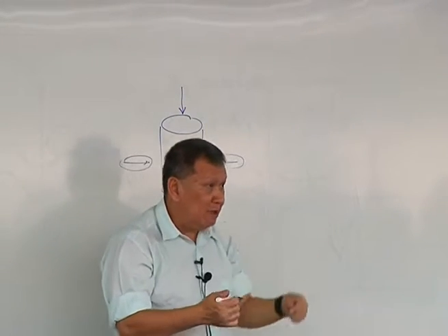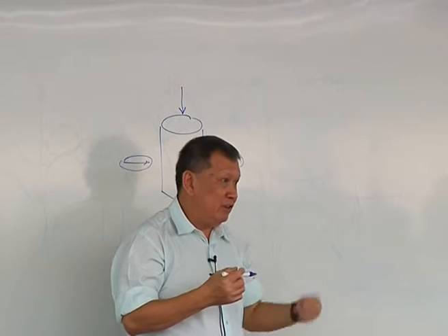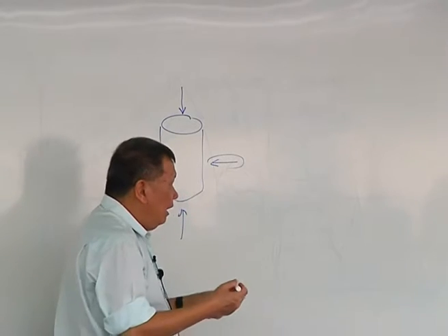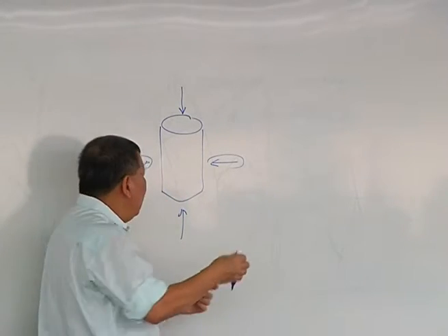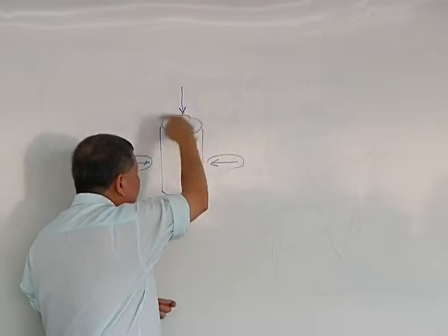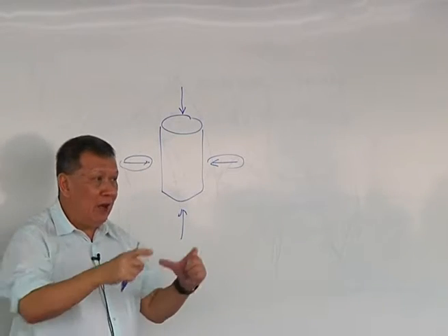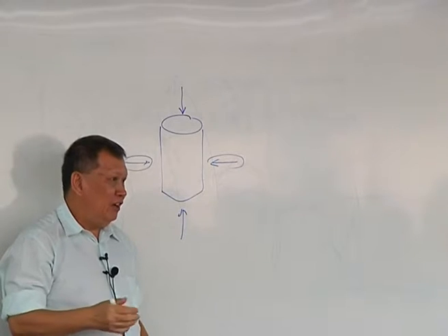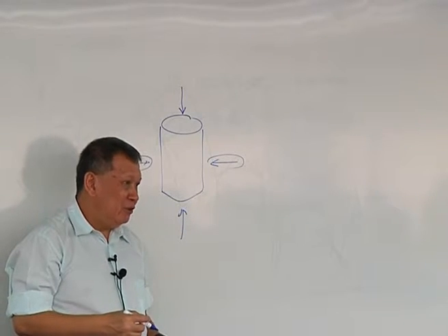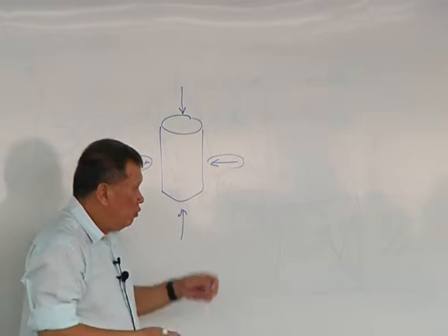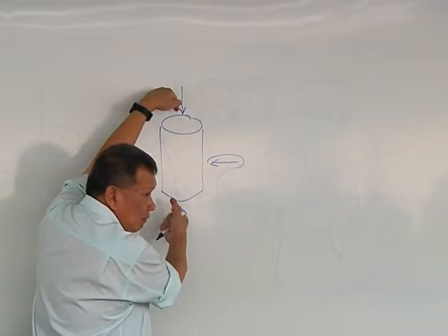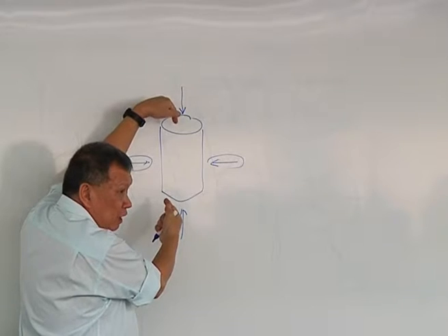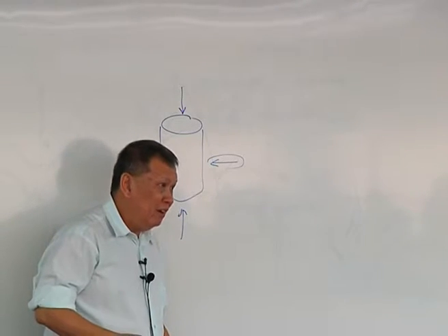Okay, basically you unload, there may be some yielding, and then you reload, there will be some elasticity. You will go back elastic because you are reducing the deviator stress. So you come back to elastic. In fact, the most stable point is when all these stress components are nearly equal. That's an isotropic condition, and that is the most stable condition. So as you start to unload it and load it back again, back towards an isotropic condition, you generally will get elastic behavior coming in.